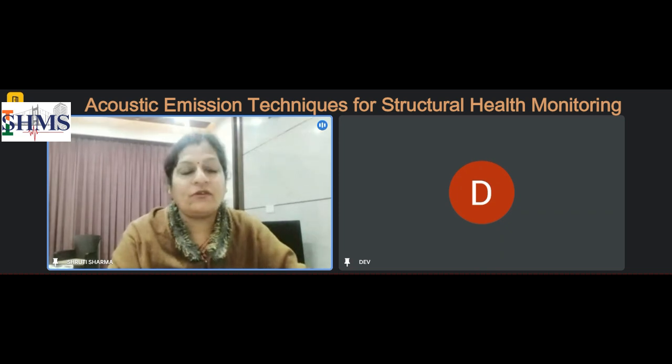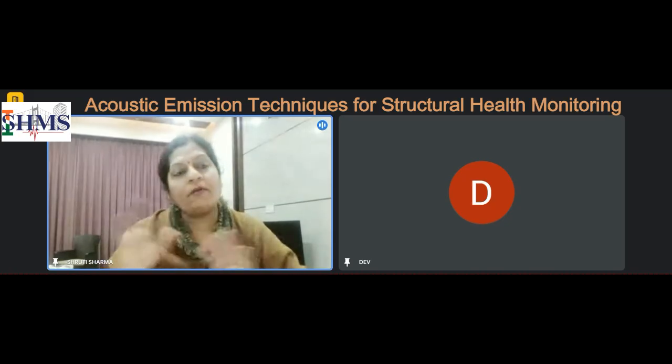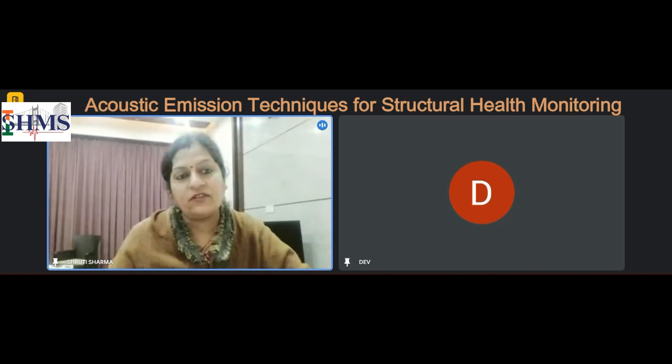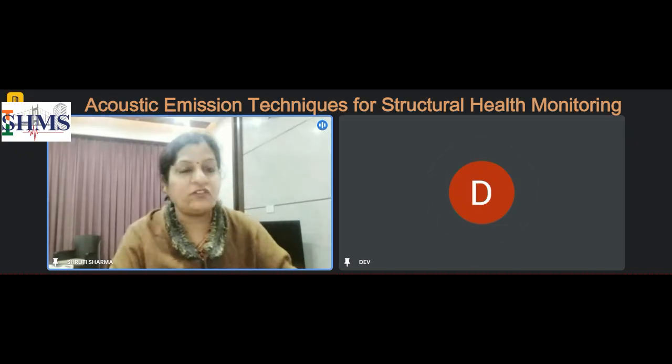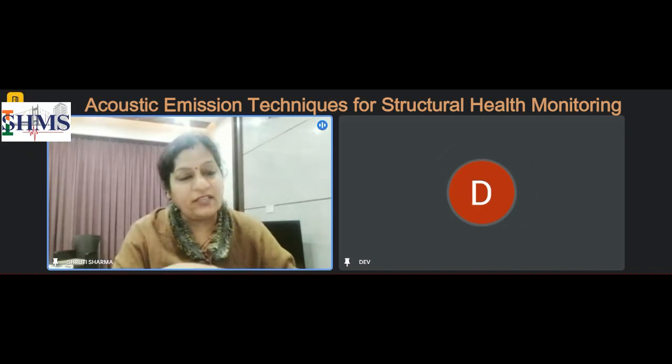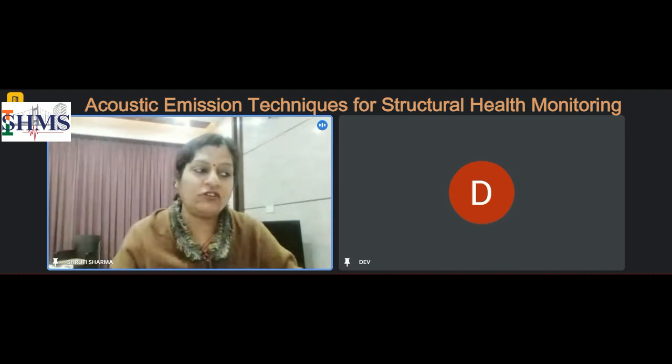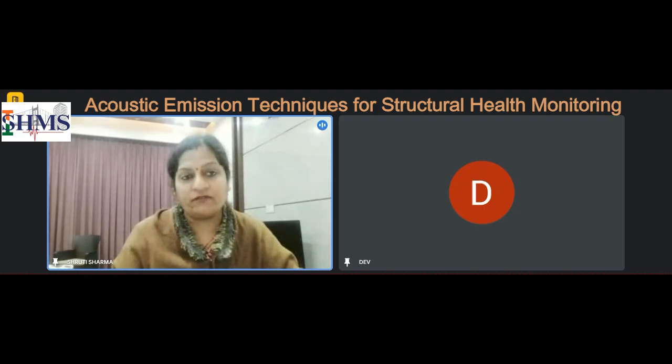This is one of the drawbacks also. Now, here the ultrasonic or other tools will come to the rescue. You may take a signal, go back, and come after, say, 1 year or maybe 6 months and take the signal again. So you can just compare your two signals. The active tools may work nicely in general kinds of buildings, but wherever it's a very important structure, we need to put the systems in place, for example, these sensors.